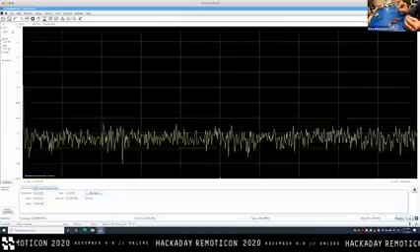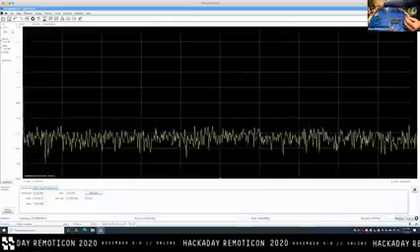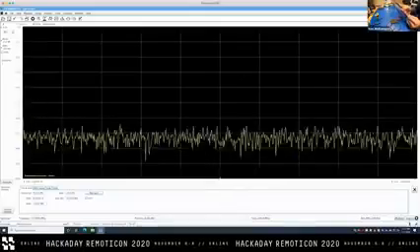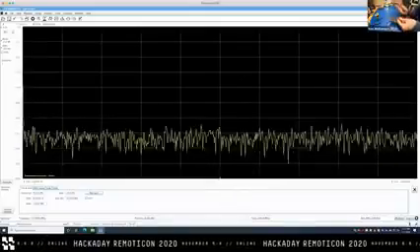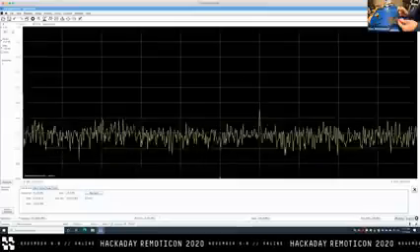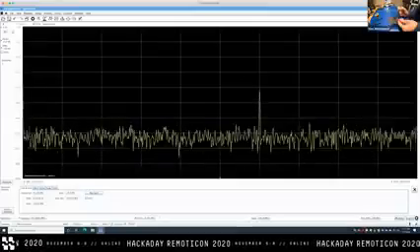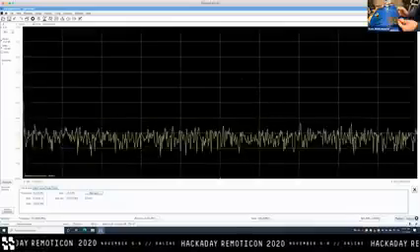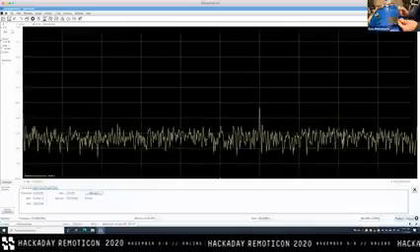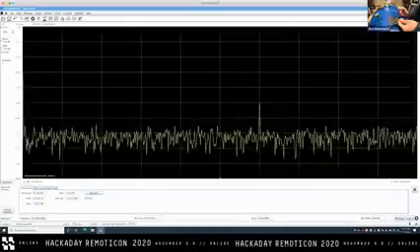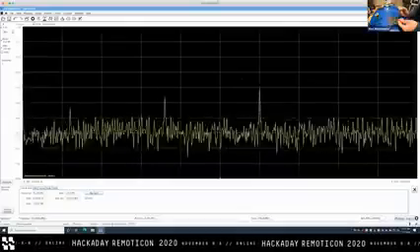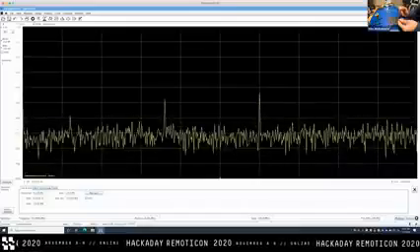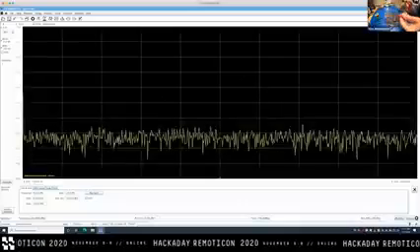I'm going to switch from the large B field probe that I have been using to a slightly smaller probe that gives a little bit better spatial resolution. And we see again, okay, the peak is lower because we're using a less sensitive probe, but we definitely see that same 60 megahertz peak. We don't see a lot of that broadband noise, which is interesting. And then we see, I'm just going to give it away, a 12 megahertz and a 36 megahertz peak down here